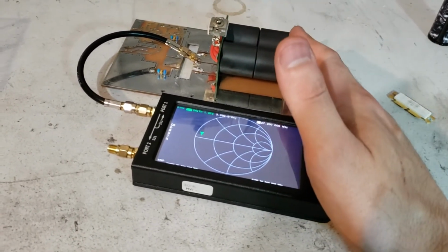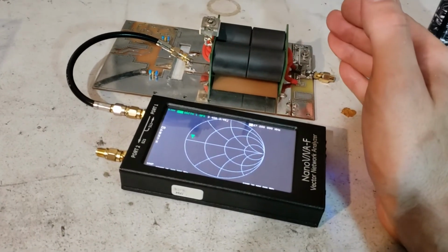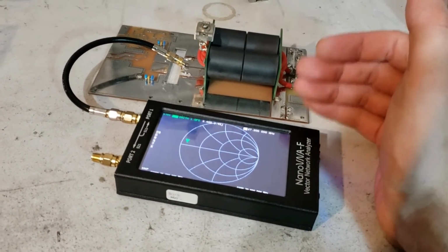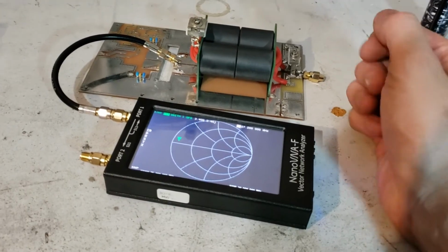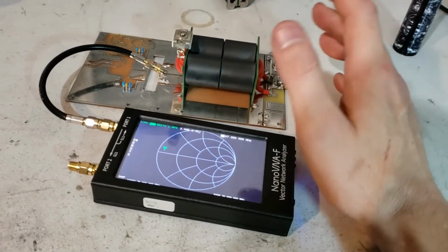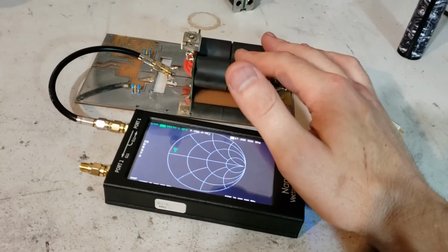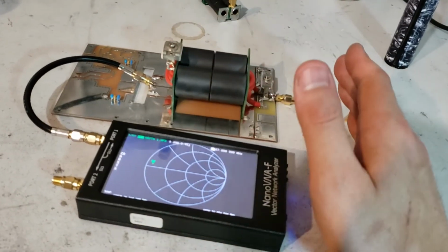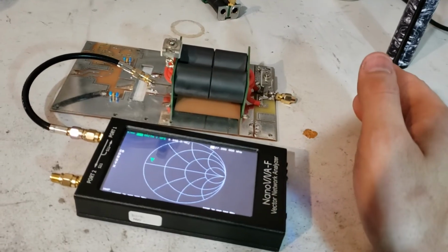When you're tuning the output transformer, you can't pay attention to reflected power. Reflected power means pretty much nothing. Deeper down the rabbit hole, that's why. So when you're tuning the output transformer, generally you pay attention to power gain. That's one good way to start.